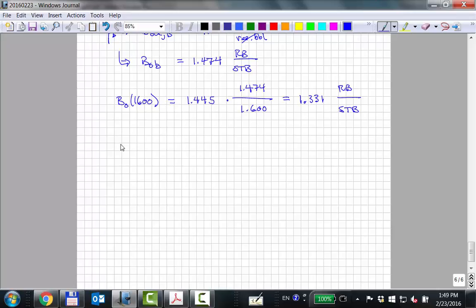the efficiency of the surface process depends on the number of stages and the pressure and temperature at each stage. It's much too complex for me to say what would be better, A or B or C: 3 stages with these conditions or 2 stages with these conditions. There's no way I or anybody else is smart enough to tell you this gives more stock tank sellable oil. It's just too complicated. What I can tell you though is that if you put all of your separator stages at the surface at reservoir temperature, that's not good.